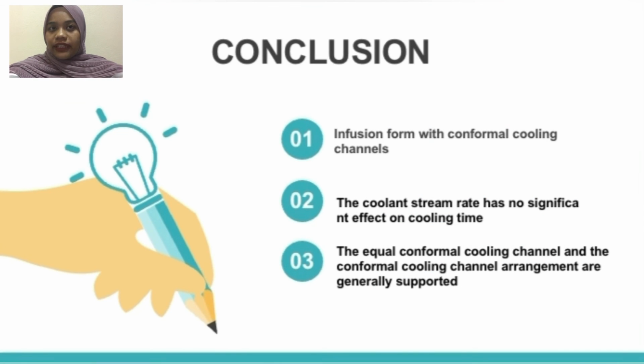Now I will explain about the conclusion. Injection molds with conformal cooling channels give a significant saving in the cooling time of roughly 89.92% compared with non-conformal cooling channels. The cooling channel flow rate has no significant effect on cooling time.